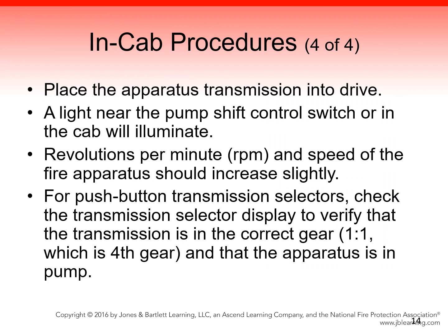Place the apparatus transmission into drive. This allows the motor to power the pump instead of the drivetrain of the fire apparatus. Upon proper engagement of the pump, a light near the pump shift control switch or in the cab will become illuminated. This indicates that the pump is engaged with the transmission and ready to pump.